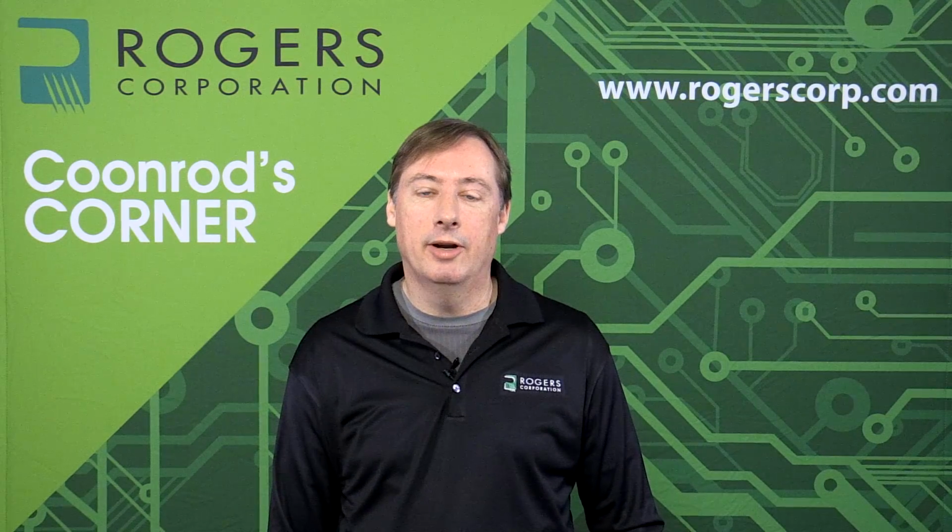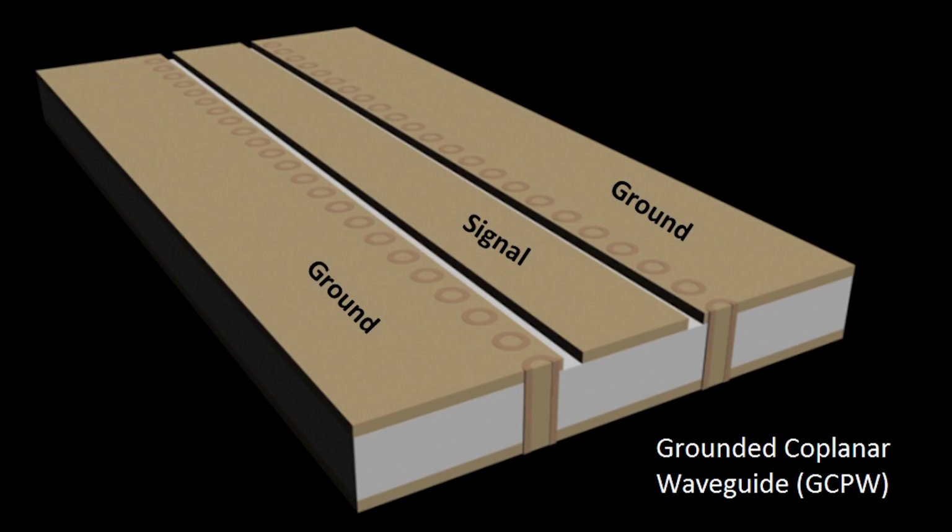Now let's consider the grounded coplanar waveguide structure. The grounded coplanar waveguide structure has very strong electric fields on the coplanar layer, which is the ground signal ground layer on the top copper layer. And because of that, you have more influences related to the circuit fabrication, where the copper plating thickness can vary the impedance more. The reason is that the sidewalls of the neighboring conductors between the ground signal ground will be taller or shorter depending on the copper thickness. So copper thickness variation that's normal in circuit fabrication can impact the impedance.